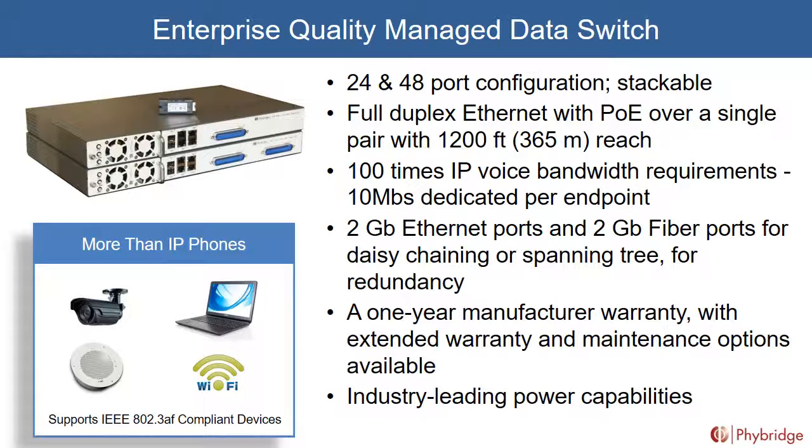And one thing to note is you can see it can be used for more than just IP phones. IP cameras, IP overhead paging systems, wireless access points, door entry systems. Any 802.3AF compliant device, we would be able to provide the power and Ethernet for over that 1,200 feet. Does that also mean I could put Internet of Things at the ends of this cable? By all means, absolutely. And this is something that we're seeing a lot of in the market today in places where internet-connected devices are required, but they just have the infrastructure.